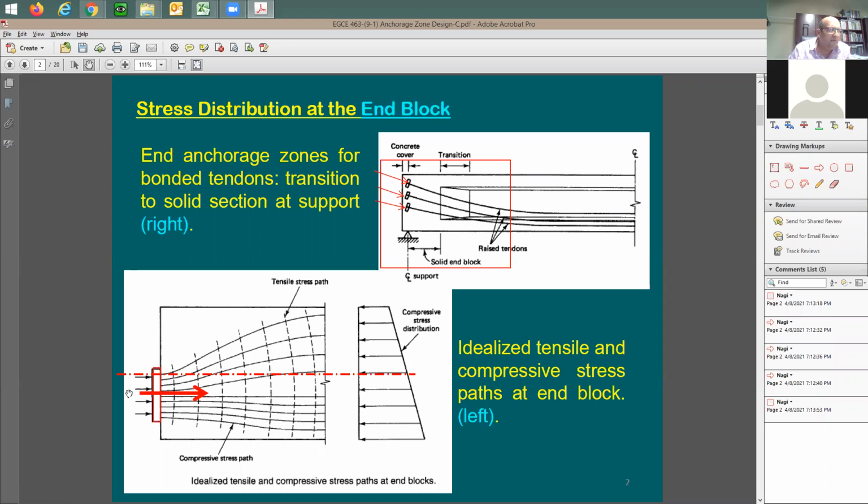So if you put the force right here, the pre-stressing force right here as compression on the concrete, you're going to give it some distance here before you have this uniform distribution of stresses. It's not going to happen right away, because think about it this way. If I put here a point load right at this location, just imagine that you put a point load right here.